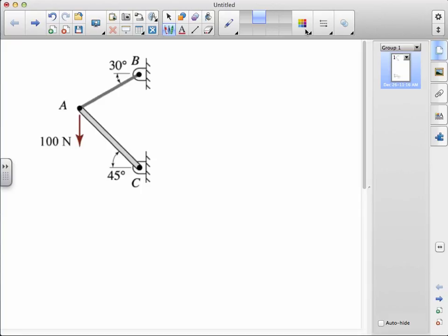The light D-shaped outline indicates a flange, and the cross-hatching indicates a rigid type of attachment, bolted or welded to the wall. The significance of the pin is that it permits the structural element to rotate freely about the pin's axis perpendicular to the page.